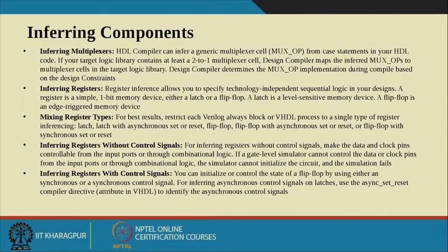Inferring components means I can infer several components using the commands in Design Compiler. Like if I want to infer a multiplexer, using this MUX_OP, I can infer one generic multiplexer cell.